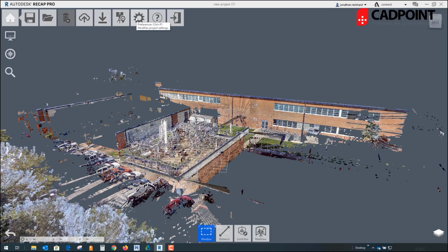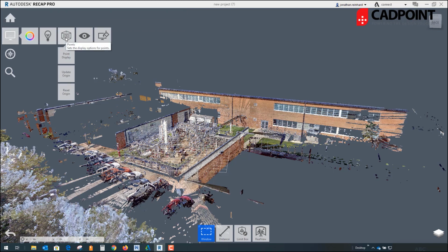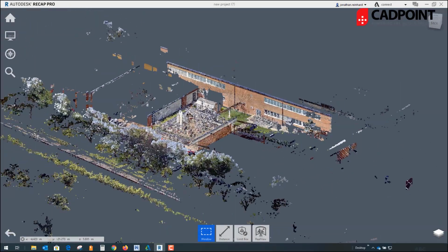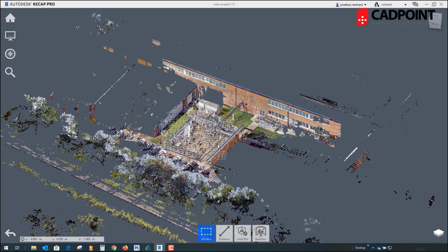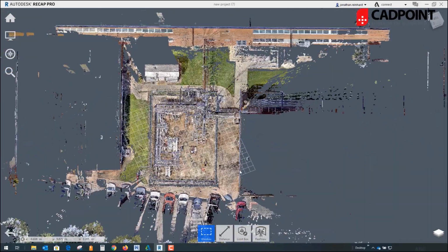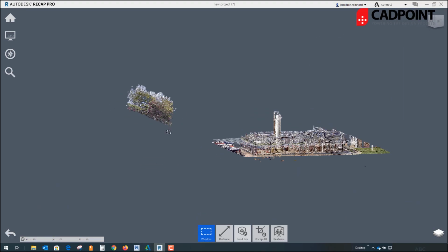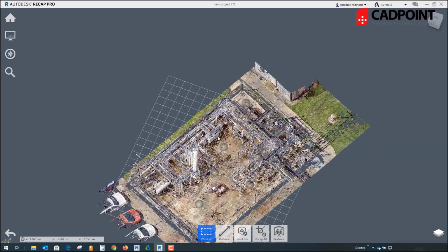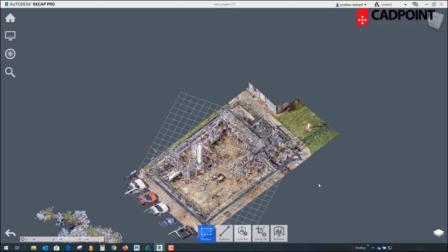I'm going to go up to my top view, or down to my view on my second tab, sorry, toggle UI elements. Perspective is enabled, so I'm going to disable that and bring it to an orthographic view. That now enables me to select elements that won't be captured in a perspective view, avoiding those obscure elements. So again I capture this, hit my window and clip outside, and I've got a nice square there, with no perspective elements brought into it. I only want to capture these elements of the site for the purpose of this demonstration.